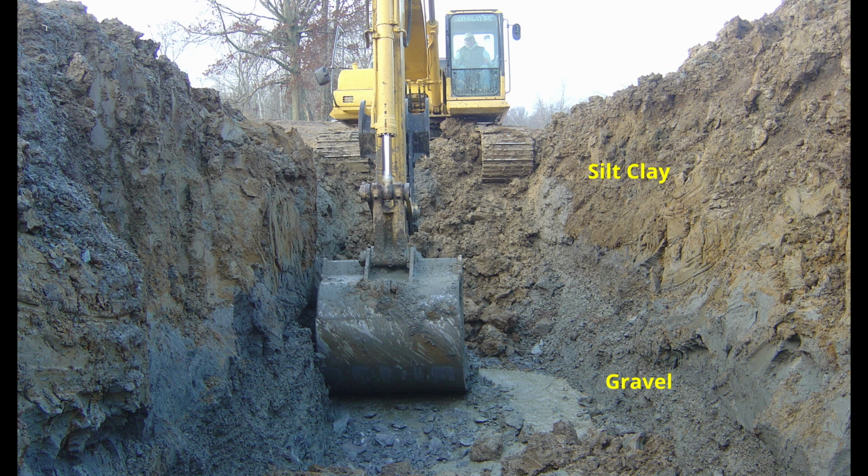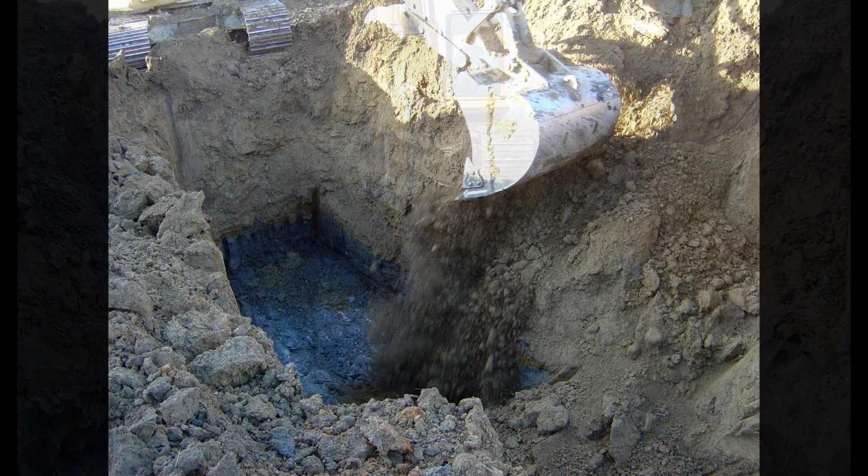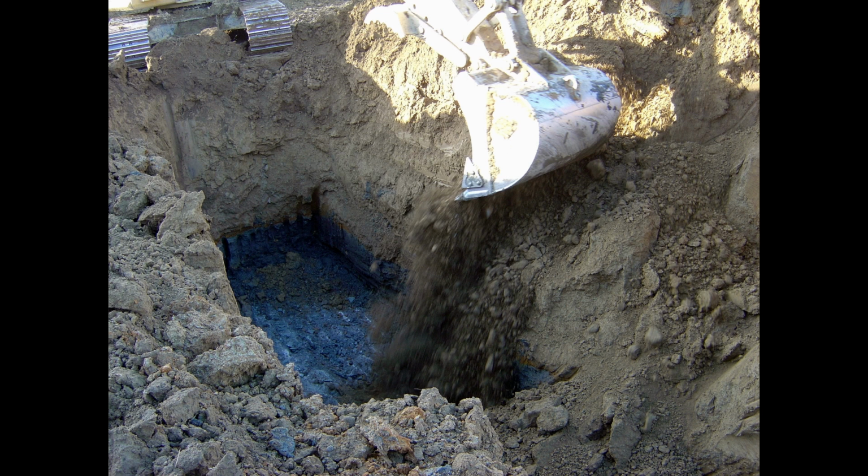The groundwater was not flowing in the silt clay. However, the groundwater was flowing in the stream channels that were underground, and these were in gravel overlaying the shale bedrock. Here the excavator fills the very bottom of the trench with silt clay to avoid a cave-in. Some sections of the trench were so unstable that one could not leave it open long enough for the dozer to spread a soil layer in the bottom.